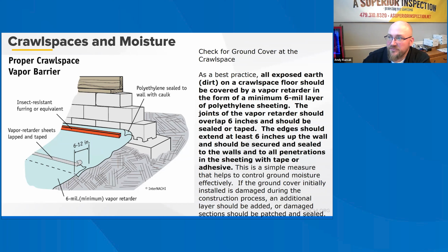Conventional practices, which require minimum net area openings based on the underfloor space area, or non-vented design strategies. Traditional ventilation calls for a minimum net area of at least 1 square foot for 150 square feet, or reduced to 1 square foot to 1,500 square feet when using a Class 1 vapor retarder. Vents should be on at least 2 opposing sides of the foundation, near corners, and high on the foundation walls. Inspectors should refer to applicable building codes before recording evaluations.